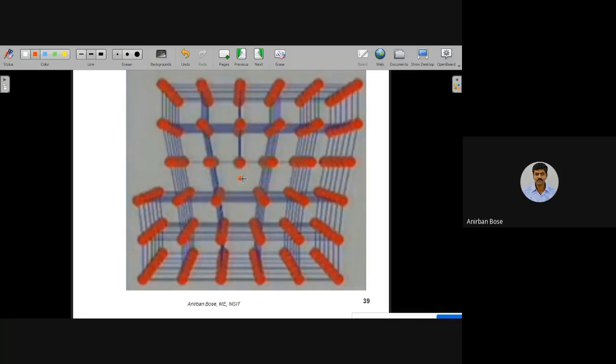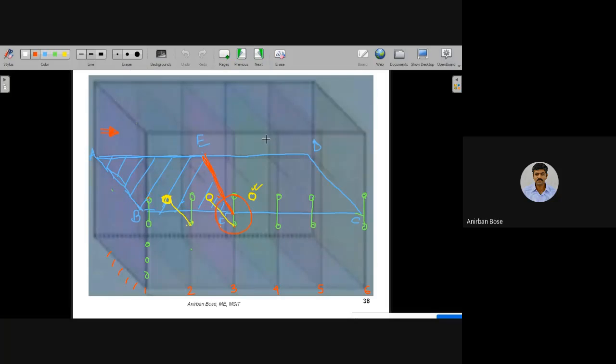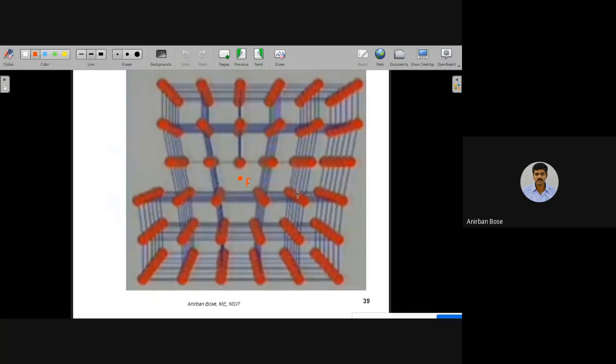point. If you go perpendicular to the plane, that line is basically, and here it is the F point that you can see from this end. If you go perpendicular in the other direction, the other side is E, because here you can only see the F point, and at the other end it is the E, and around that line you will observe these defects. Above this line you will find the atoms under compression, and below that line you will find the atoms under tension. So this is the edge dislocation.